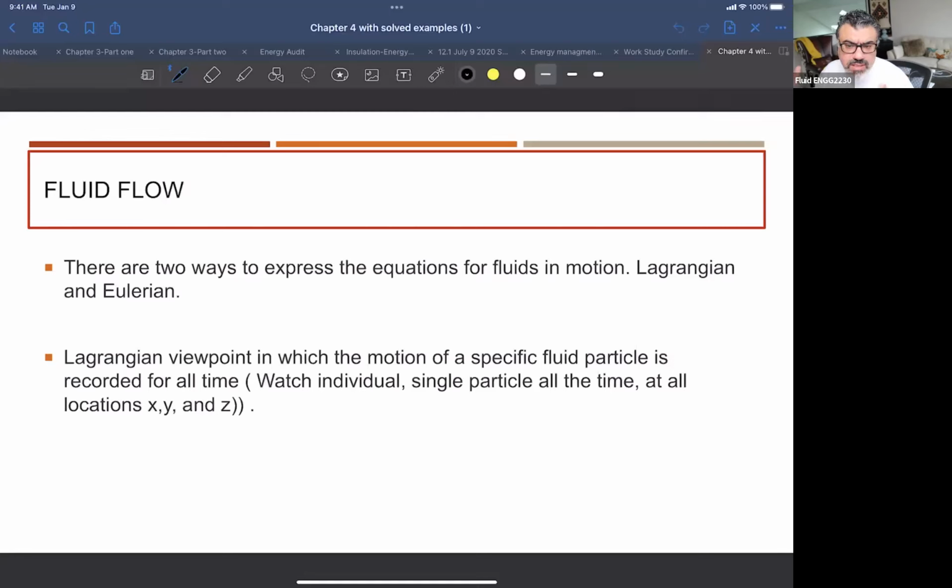Let me give you an example. Like rocket engines. In many rocket engines, in order to increase the thrust, they add certain kinds of droplets into the air or the combustion gases in order to increase the mass. But those particles can generate some erosion in these thrust nozzles.